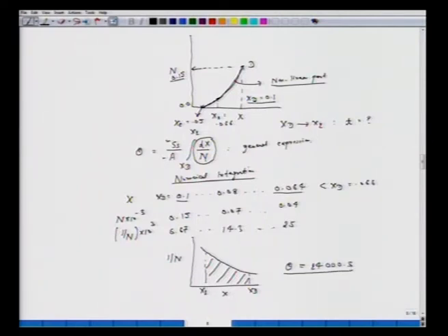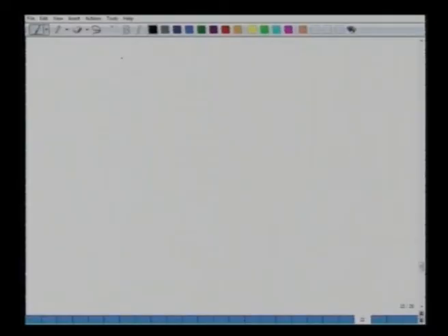So we have all three times for the total drying time. First, remember, for the constant rate, it was 16,000 seconds. This is the time over which the rate remains constant, and moisture dries at a constant rate.